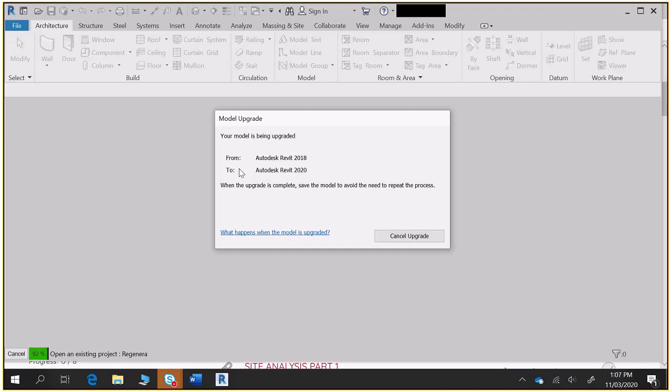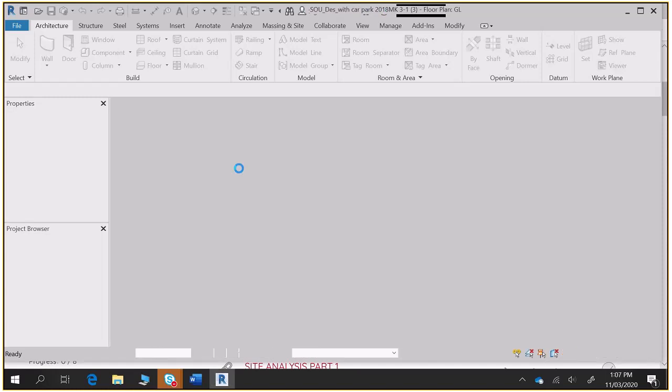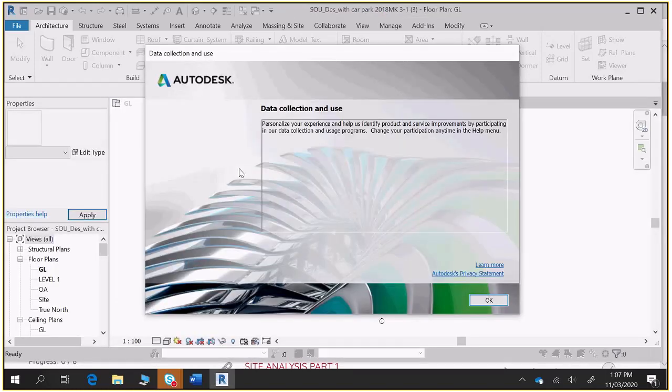With this project, project number one is really simple in terms of council and planning. It's completely appropriate for the planning, the zoning and the locality. Super simple. This one gets far more complex in regards to requirements for private open space and car parking, because the requirements for private open space hinge upon the number of bedrooms in a unit. So you need to dissect the council-wide objectives a little bit more in your planning, because it has further implications.